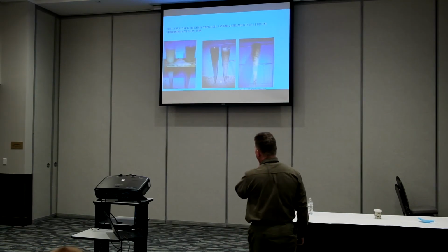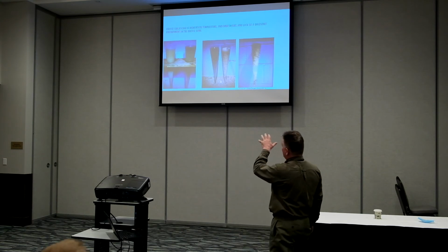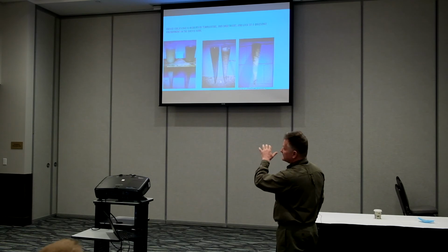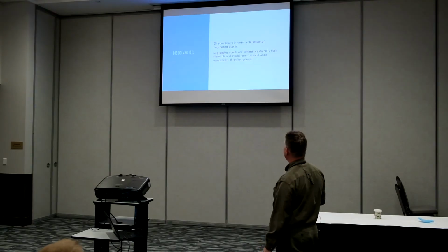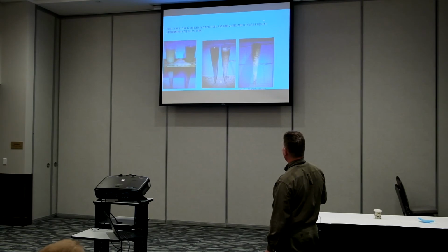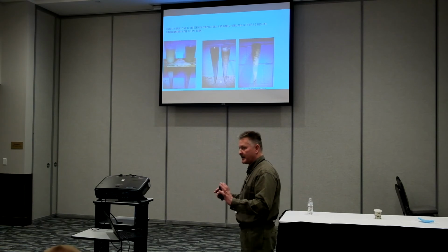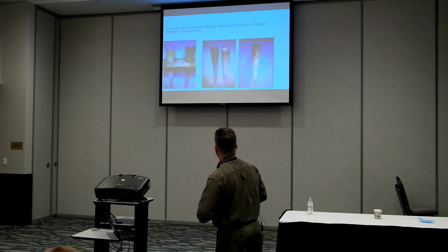It's kind of hard to see in this picture, but the coalescing of grease and oil is reduced. We have to keep this in mind when we're designing: it is reduced by temperature, emulsifiers, and the lack of a quiescent environment, a nice, quiet zone for that separation to occur in the system.